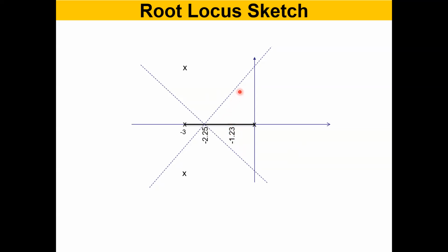So at some point of time, as they reach infinity along this asymptote, they're going to cross over to the positive half plane. And that is where the system becomes unstable. Okay. So how to calculate the maximum stable gain of the plant?